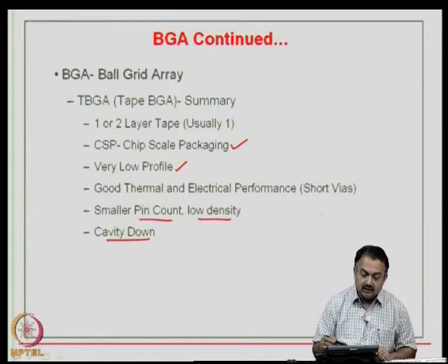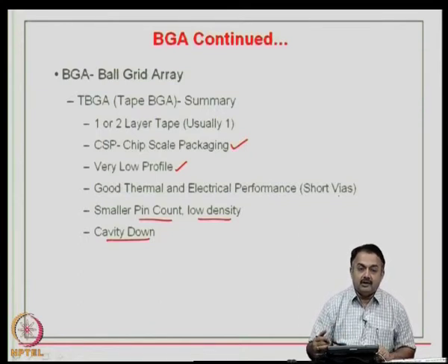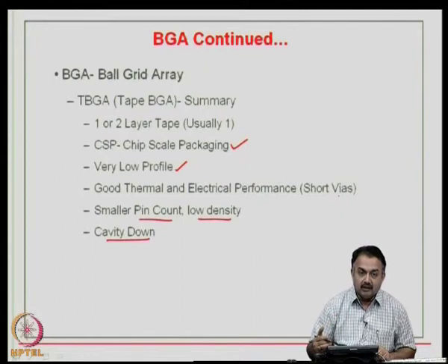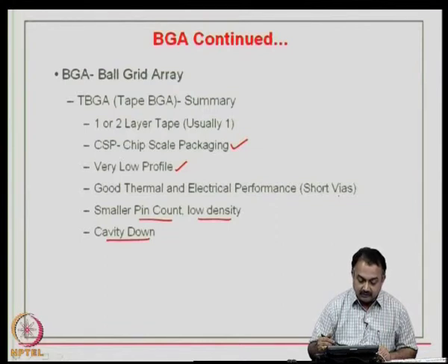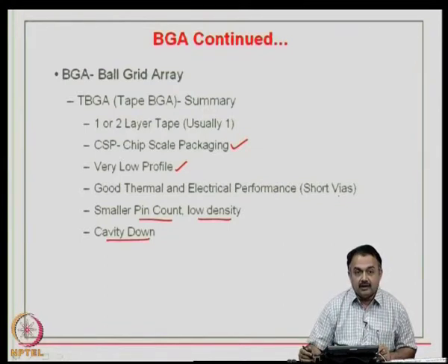So, basically you can expect the features to be available on a tape, and then you have the bonding taking place between the die, and the ball grid array typically comes in a tape format, and then typically a tape ball grid array is not very common nowadays. Most people use plastic ball grid arrays, and for high end applications we use a ceramic ball grid array.